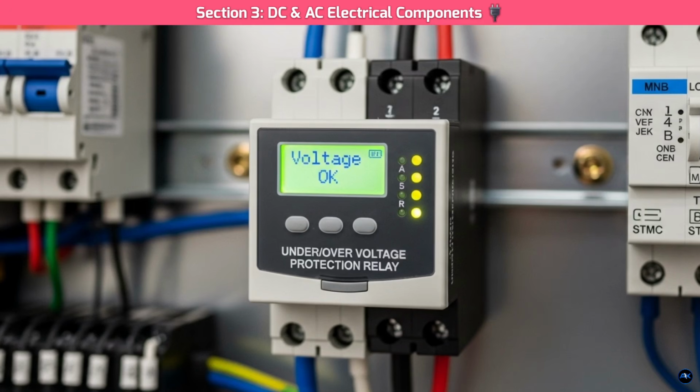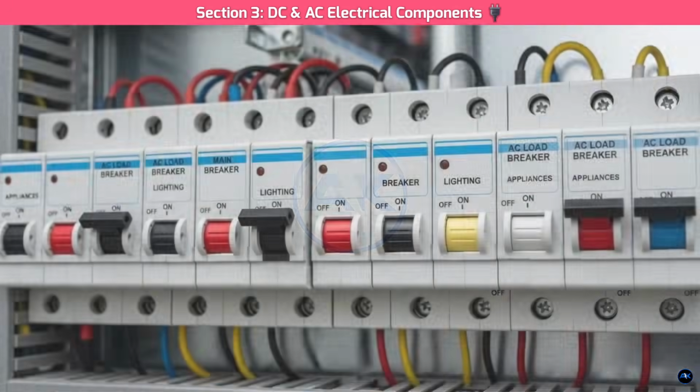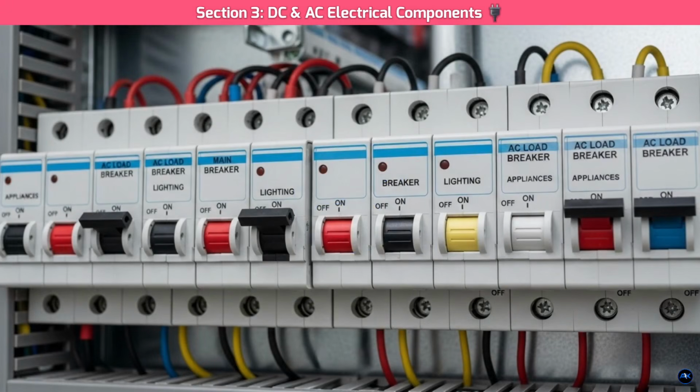It should be a three-phase relay rated for a 400-volt system with an adjustable voltage range to prevent nuisance trips from small fluctuations. Component 5. AC load breakers. The final components are the AC load breakers. While not directly part of the solar system itself, they are critical to the overall panel's safety. These are the standard breakers that protect the individual circuits in your home, like your lights and appliances.